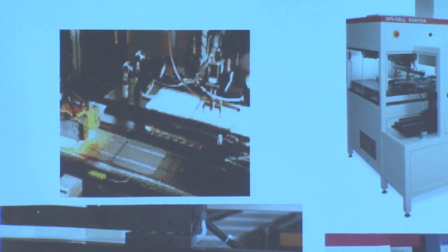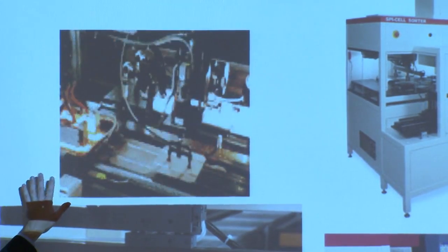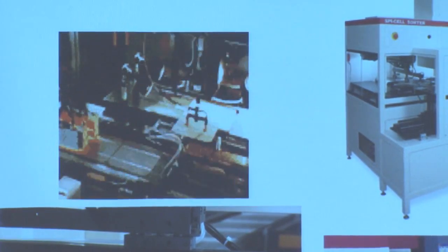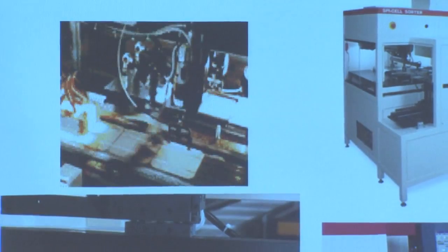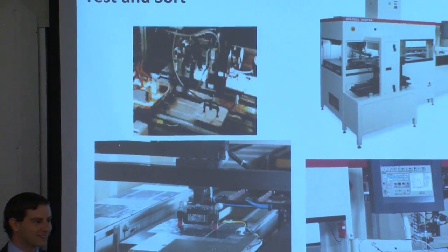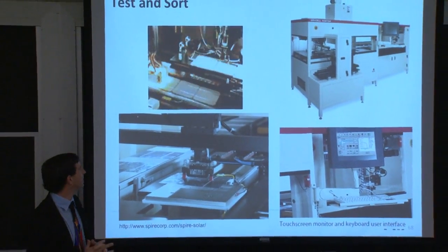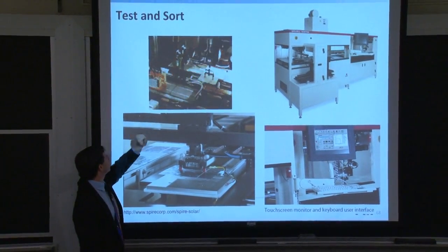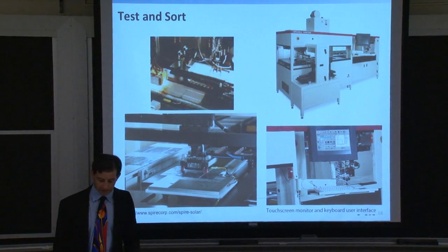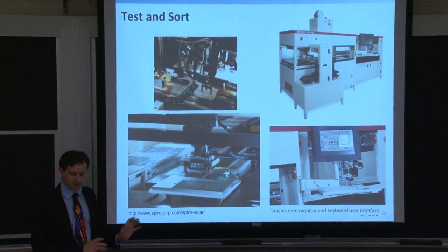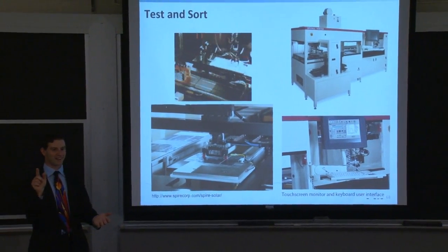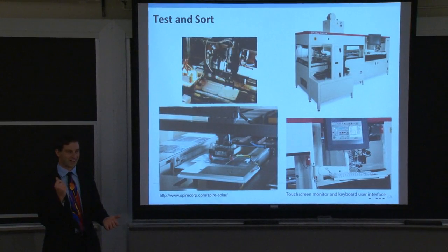I can't really tell from the photograph or from the movie right here whether the IV curve is being swept at illumination, meaning you're sweeping your voltage when the cell is illuminated, or whether the illumination intensity itself is used to vary the forward bias condition of the cell. They could be doing it in one of two ways. But most likely what they're doing is they're flashing the light, measuring the IV characteristic of the device, and then sorting the cell based on that performance. It goes into a computer. Efficiency is calculated, just like you did on your homework. Just like that, it's calculated.